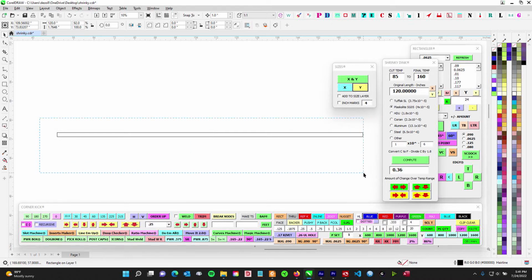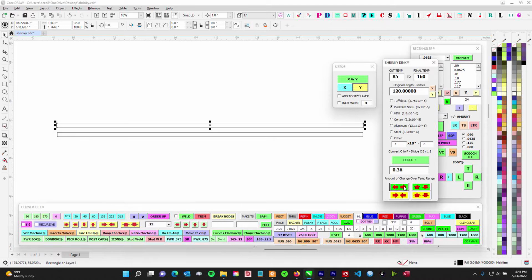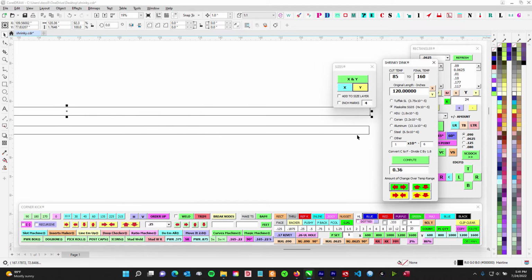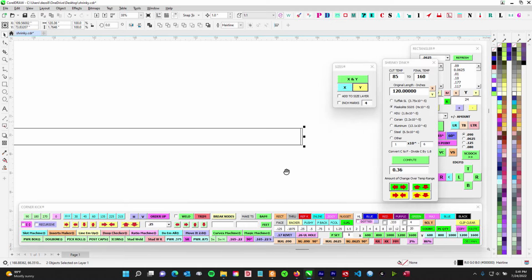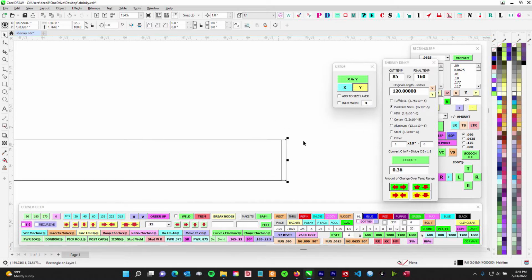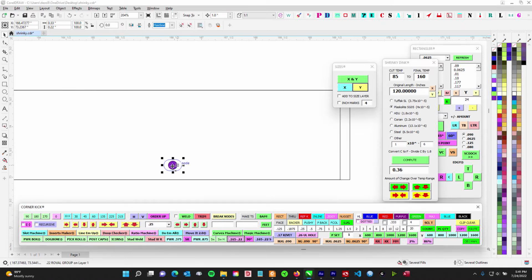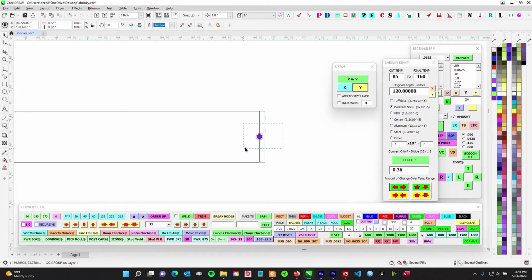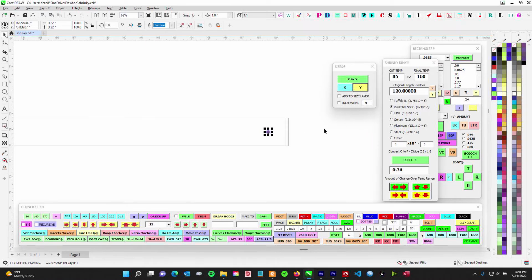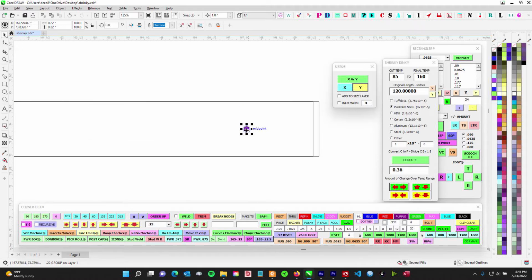So if we do another one of these, and then we add it, and then we recenter it again, you can see how much this bar wanted to move. Now, if you also take a stud hole, actually I'm going to do a straight stud. So this is for a tap 10-24 and a clearance hole of 0.22. And let's say we put that in 2 inches from the edge, then you go here and you move this 2 inches in from the edge.